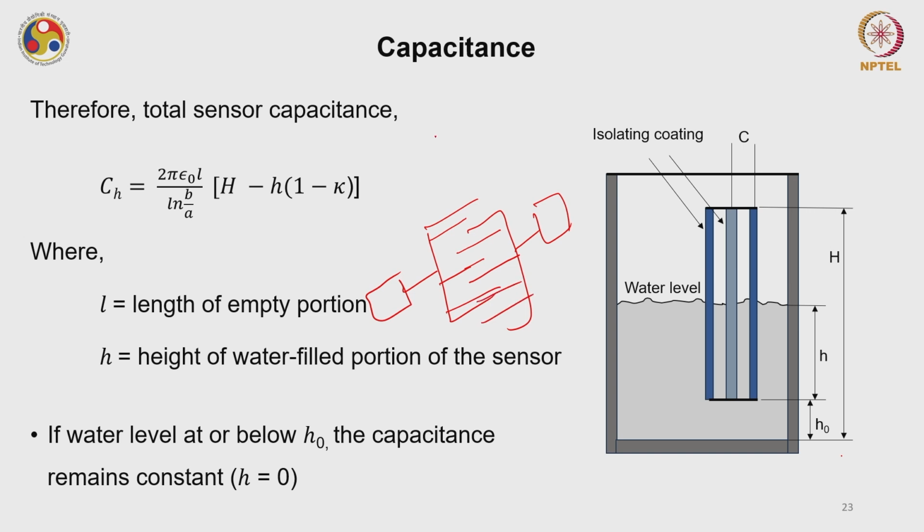The same interdigitated electrodes that I used to explain the gas sensors. Or let's take an example of gas sensors only, using the capacitive principle. This is my transducer, which is simply an interdigitated electrode. Now my receptor is an insulating material, or it can be a semiconductor also, depending on the temperature or frequency of its operation.